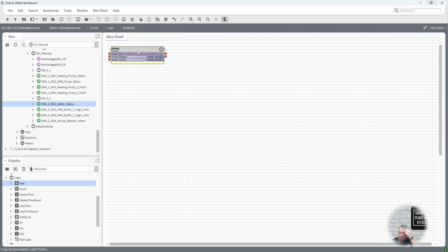Now I presume we would need a time clock for when they want the heating on, and a time clock for when they want the hot water on. And I presume because they've got outside air temperature, they want to also stage the boiler set point with the outside air. So if it's hot outside, the set point wants to be lower than if it's cold outside.